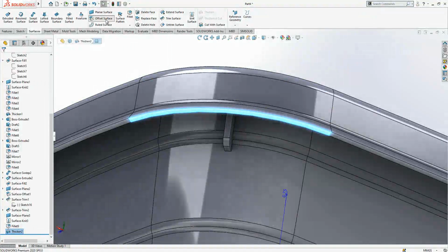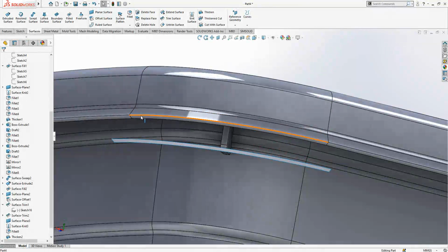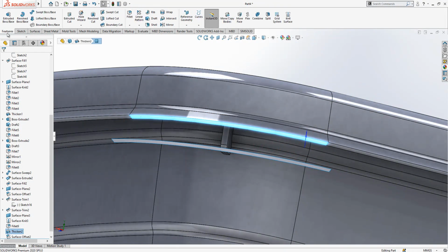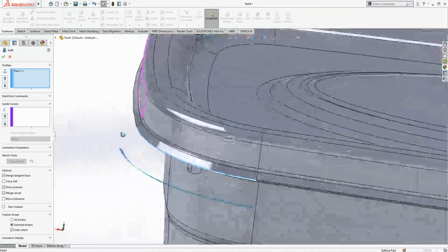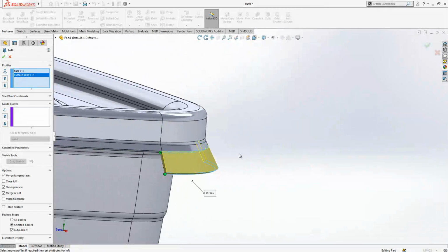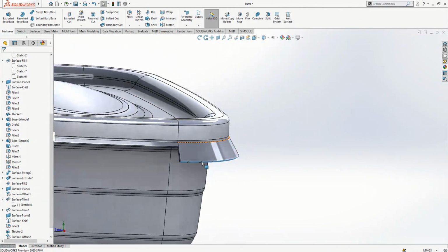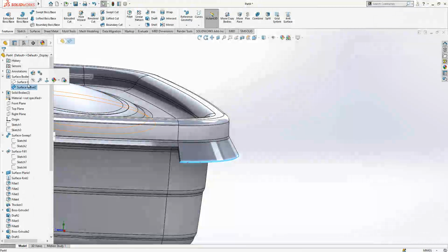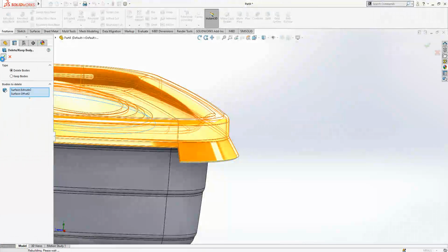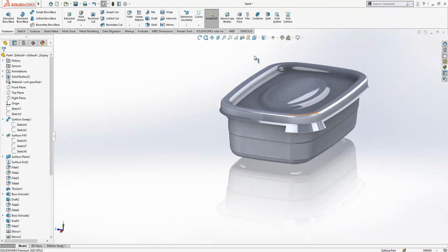This is a nice example as well. We are going to make here an offset of 5 from the surface. Between that offset and the surface, I will make a loft. So many people will not know this. You can make an offset loft by using existing surfaces. Auto select only this body. This body, the result will be combined to this body. We have here unnecessary surfaces. From operations, we can delete them. So something like this is created, guys, if you look at that.